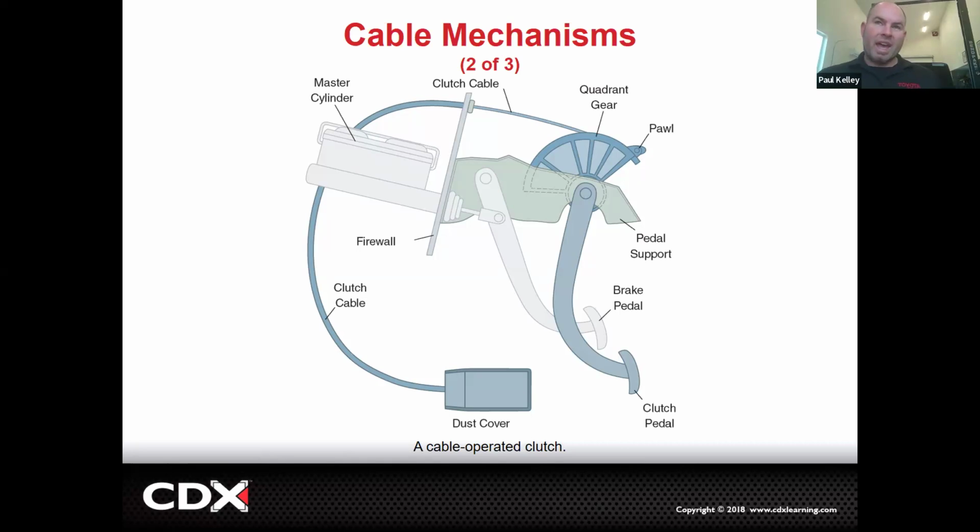So this is what happens. As it wears, the disc gets thinner and thinner. We need to continuously loosen the cable up, loosen the cable up, loosen the cable up. That's what we do, right? To make room, to allow that release fork to go further and further in to make up for the disc getting thinner. So with that, some of these things are kind of fun.